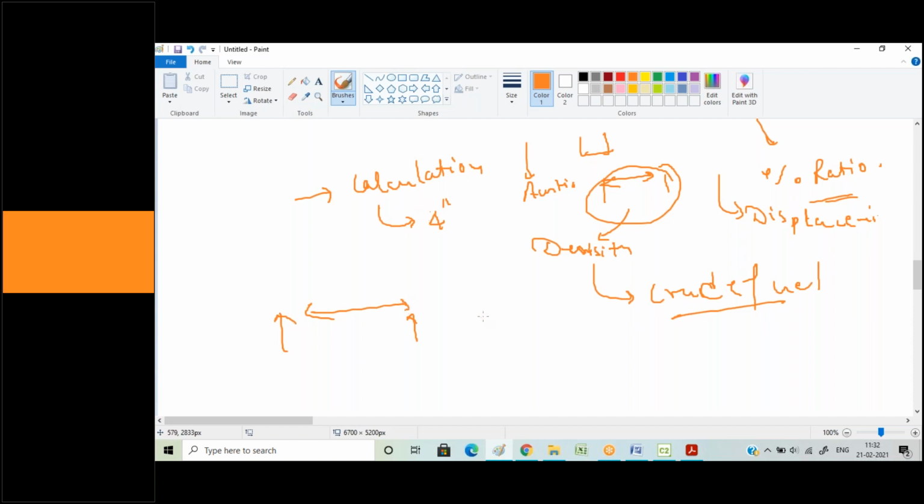Now, span calculation has a certain formula. We'll be telling you that formula, but again that formula does not consider density, so it will create some issues for you. So basically what we have for you is Caesar, which will give you the exact results of where you're supposed to place your supports in order to pass in sustained as well as operating conditions.